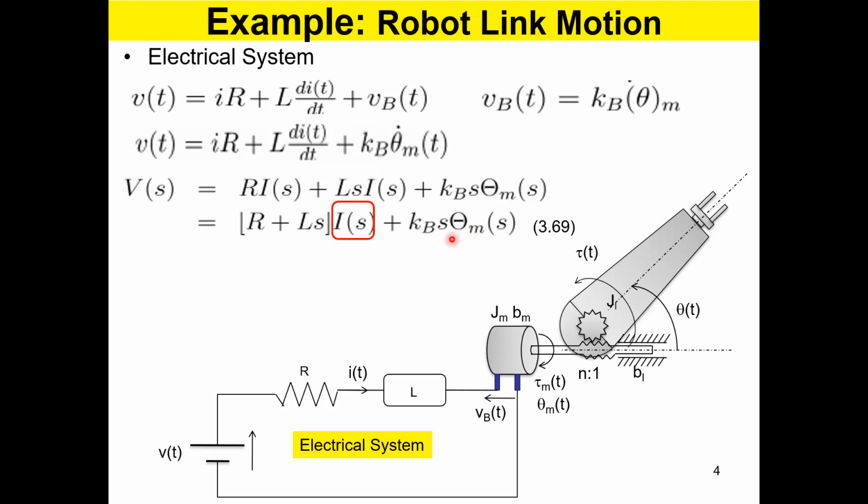Now, I can also see that theta M, which is the motor angle, and the load angle, this theta, they are related. So I don't have any problem with this one, because theta M is actually n times theta. This is a reduction gear, as you know. When this shaft turns about 100 turns, this turns 1.